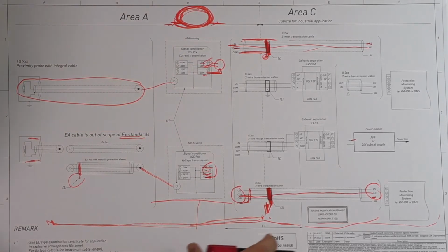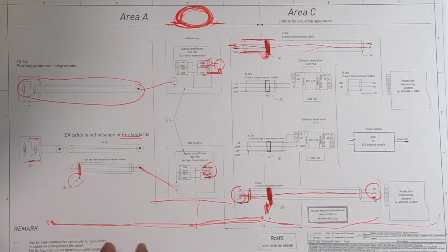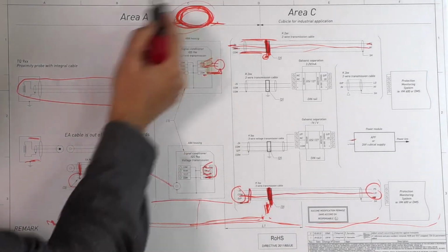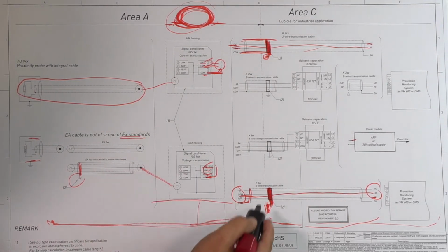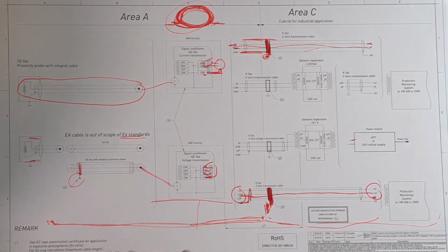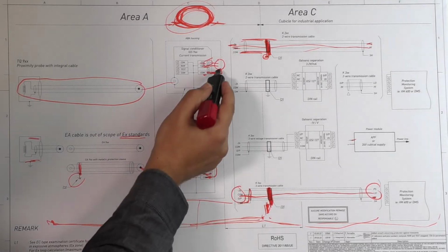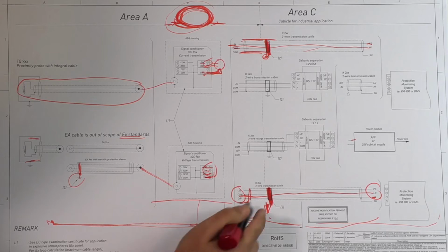If you have two cubicles, you should apply the same rule. So at the entrance of each cubicle, and also in the exit of each cubicle, you should have a good solid connection. As a summary, consider it shielded only on one side. Be very careful with this connection to the ground and with this connection to the shield. Sorry, here is to the shield as well.